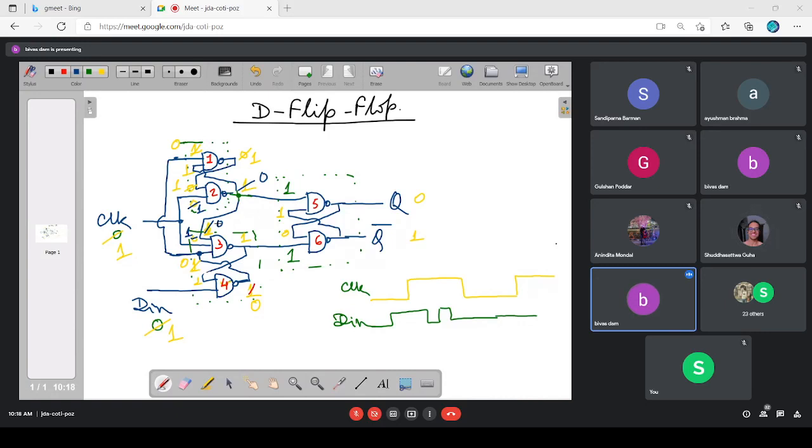No, sir. Fine. Now, that means this is no longer 1, this is now 0. Now, what will happen to the output? Q1. 0. No, Q will be, sir, 1. Oh, yes, sir, 1. This one will come here, and Q1 will be 0. Fine. So, as soon as the clock becomes 1, as the data input was 1, I am getting the output to be 1.